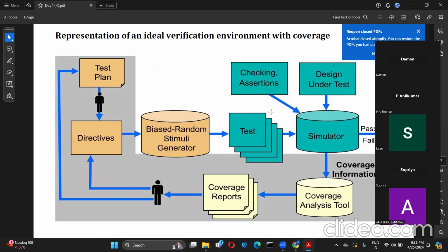If it is statement coverage, are all lines covered or not. If it is branch coverage, have the set of conditions been covered or not. Path coverage means whether the sequence of operations has been covered or not. FSM coverage means whether the transition from one particular state to the other state has been covered or not. All this comes under code coverage.